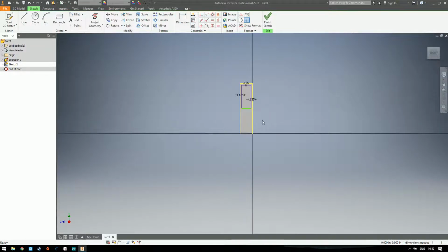By the way, if everything is set up correctly, there should not be any green line appearing on your sketch, because that means you probably didn't offset it by a bound. If you offset by a bound, the bound is going to show in yellow. If the thing is locked, it cannot move or change, it's shown in purple.